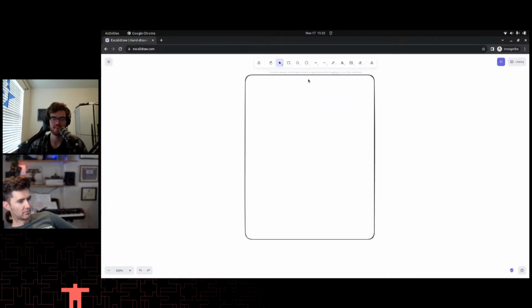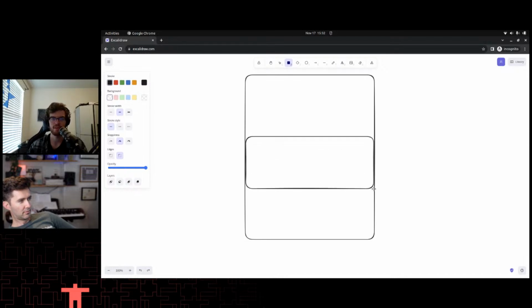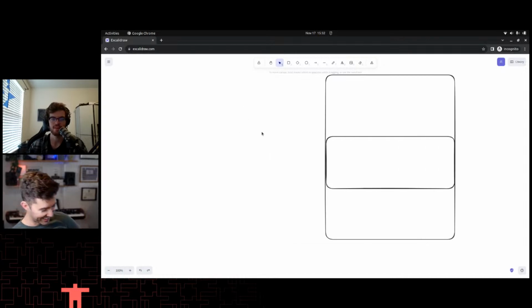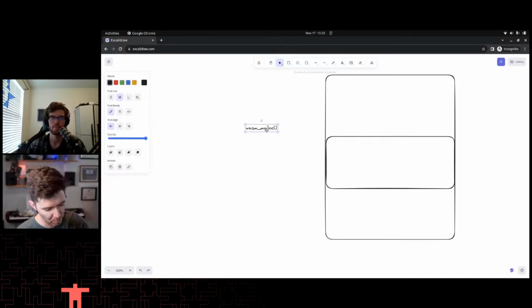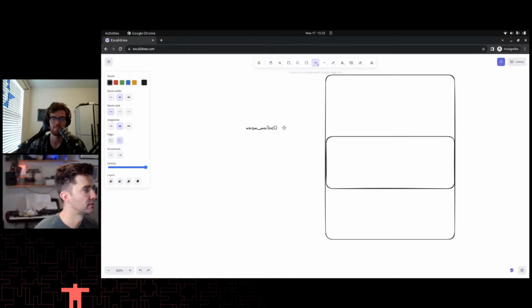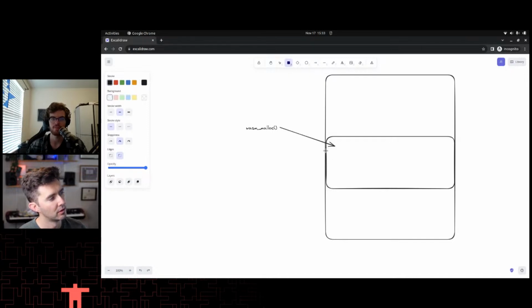But I do think that if we have the memory space that Zephyr is existing in, and we take a portion of it and say, hey, this is where our WASM memory black box is. Yeah. So what we're saying here is, our code is executing and we're doing a WASM malloc, or I don't know what the full call was, but that is saying, hey, remember that memory space that we set aside for our WebAssembly module? Get me a pointer in there to a buffer, of like 100. So give me a pointer to that.